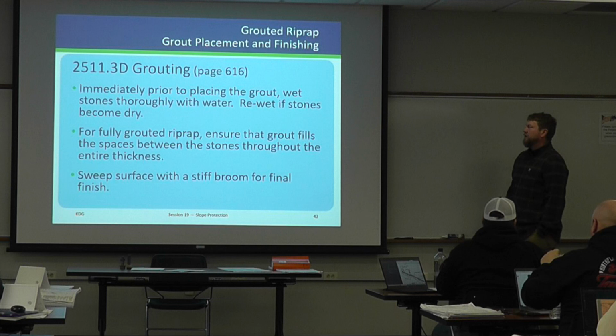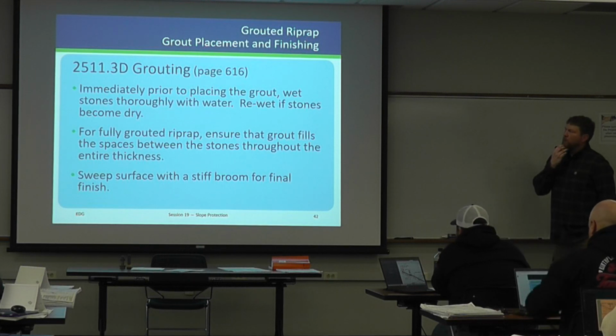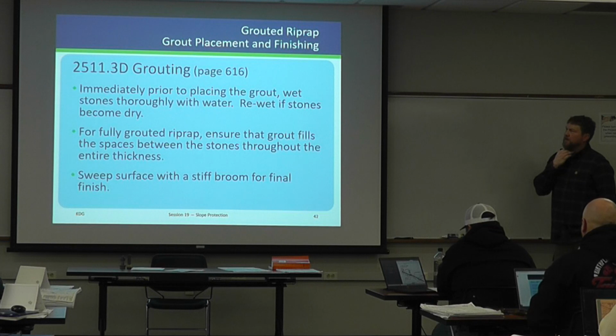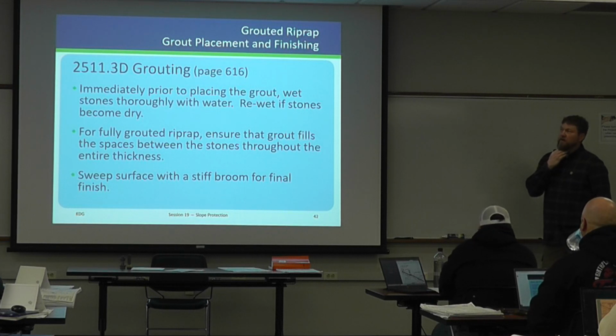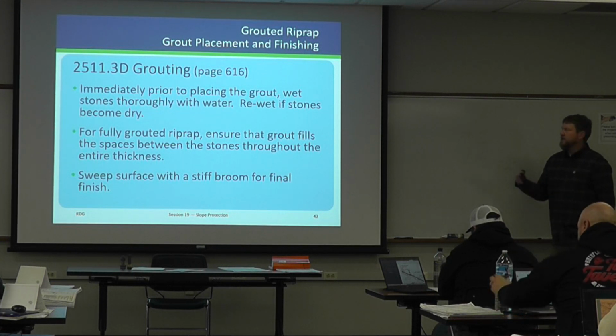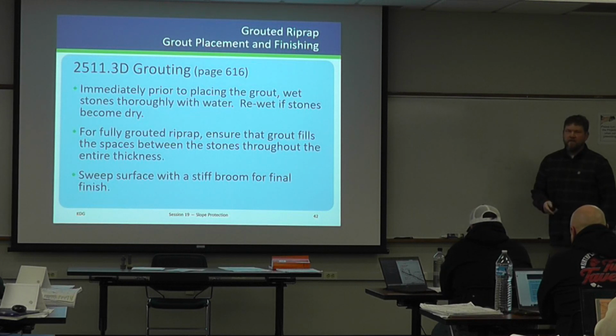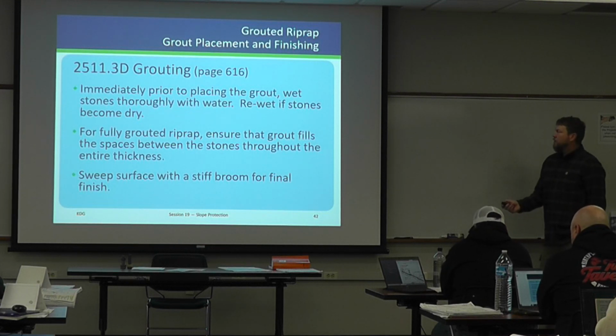Grouted riprap. Well, we're wanting to make sure that, I guess, concrete needs 2 things. It needs water and temperature. So this first bullet point, before we're placing grout, we want to make sure that the rock is wetted. If it's an igneous rock, it's probably not as big of a deal. If it's sedimentary rock, you definitely want it wetted. We don't want that underlying material sucking moisture out of the concrete. So pre-wet it and then re-wet it when needed.